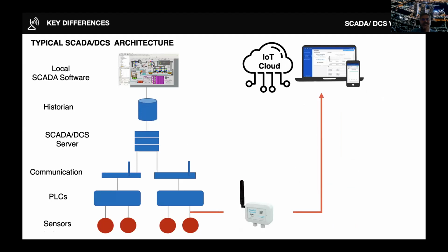The other approach is you can have a parallel system, right? So you already have sensors which are connected to some local controllers. What you do is you have a parallel connection to our device, and then the data directly goes to the cloud. So you kind of bypass all of this and the issues around warranty and the issues around negotiating with the SCADA vendor and stuff. So this simplifies your job of connecting your existing sensors to them.